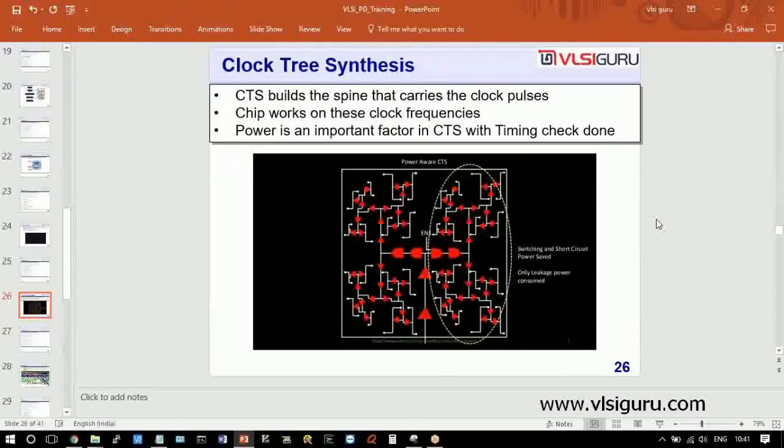Okay, you can have it provided you want to control the flow of the clock. Otherwise, you should not have it. There's something called unateness of a cell. Buffer is a positive unate cell, inverter is a negative unate cell. From this result, you can understand what a positive and a negative unate cell is all about, right?